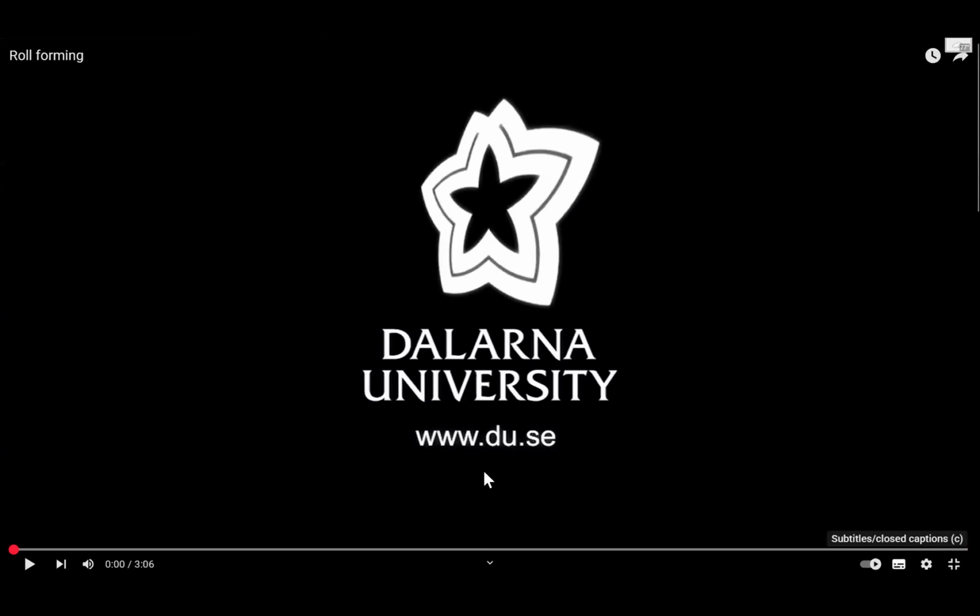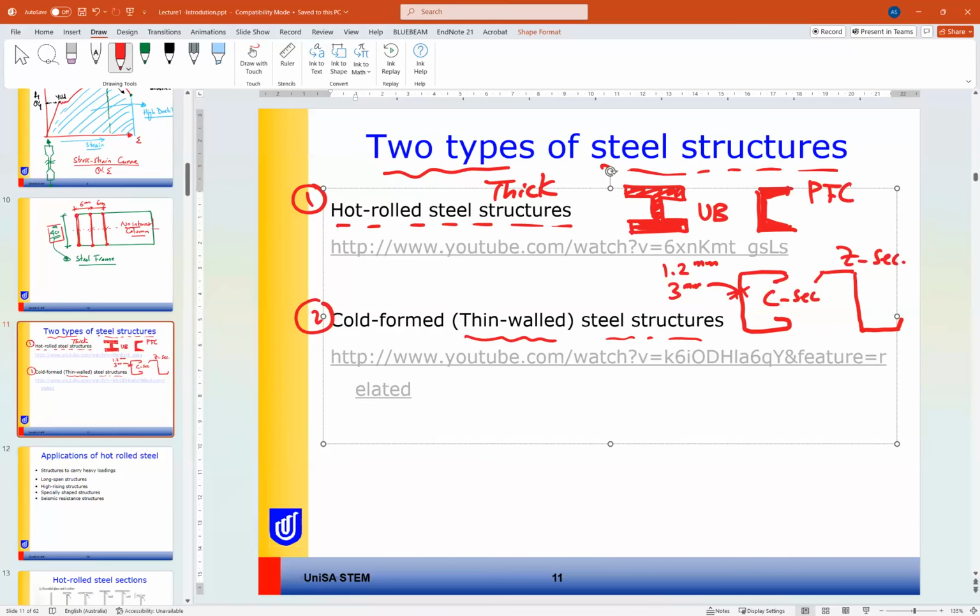Okay, guys, let's return to our lecture. So the main difference, as you can see, is that cold formed steel is rolled at normal temperature without applying any high temperature to the steel, and that's why we need very thin sections or plates to be bent to form the cold formed steel section. So they are different techniques for manufacturing both steels, but both of them have different applications. That's why we need both of them.